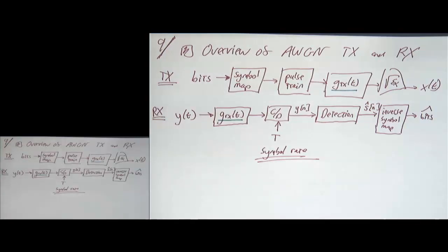That noise spectrum is flat. So if we don't filter it at all, we're going to pick up noise from here to terahertz, which is not good. So at a minimum, we want to filter just to band limit the signal so we don't pick up extra noise. But we're going to show that that filter actually has a very special property that's going to be called a matched filter.